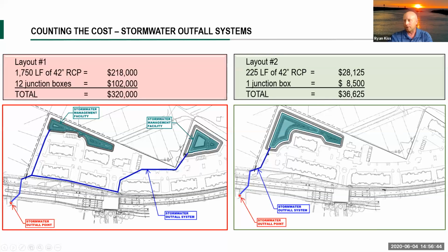And there are some very subtle bends through here that we had to hit because we had to keep it out of the city right of way and also try to keep it away from the building. So there's probably more through this stretch than what you're seeing. But pretty much anytime there's a change of direction in the pipe, you can't bend concrete pipe. So you've got to put a structure in there to be able to make that turn, even if it's a very subtle turn.